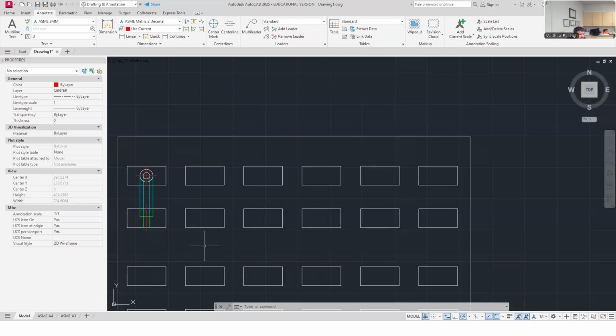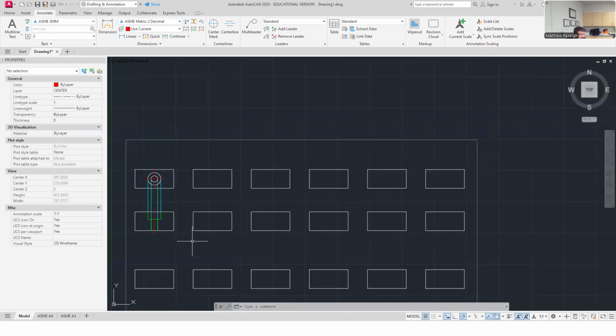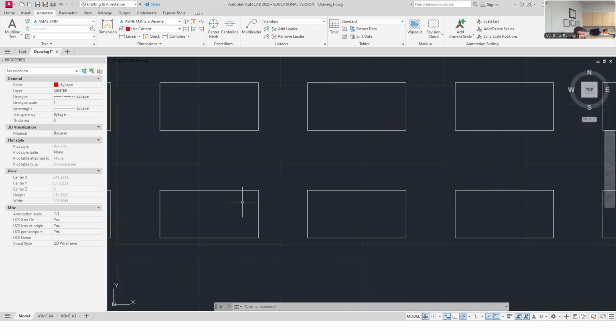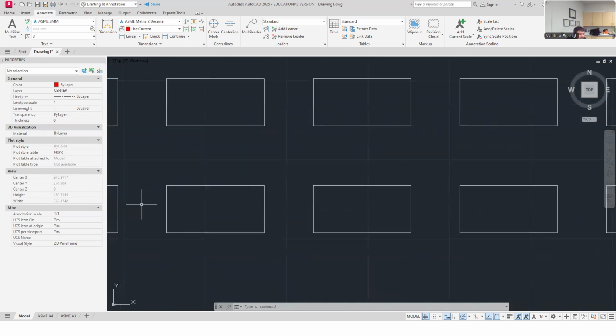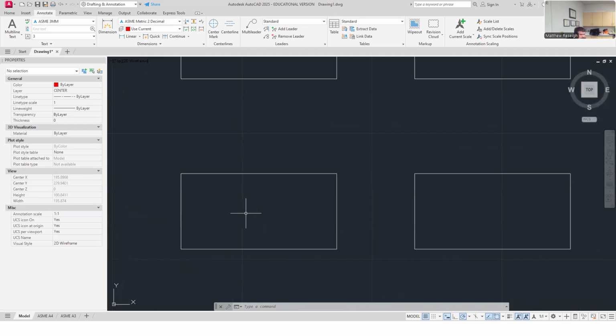And then, let's do the next one, which is a chamfer. So chamfer we've already kind of used. But what I'll do is the chamfer right here in the front view, and then I'll project it up to the top view, and it'll help me draw in what the chamfer would look like in a top view. So in the front view, we'll use our chamfer command. It's a 2x2 mm chamfer.